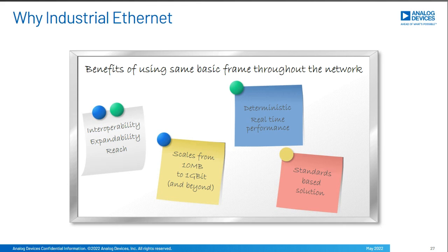Now, someone could ask, how can Ethernet be deterministic if, when connecting to the internet, sometimes loading a website takes a variable amount of time, and sometimes the website doesn't even load when the connection is not good? And the answer is, well, traditional Ethernet does not, but industrial Ethernet does. And it does so by using low latency PHYs, physical layer devices, in addition to something called time-sensitive networking, also known as TSN, which makes industrial Ethernet a real-time communication protocol to guarantee latency and determinism.